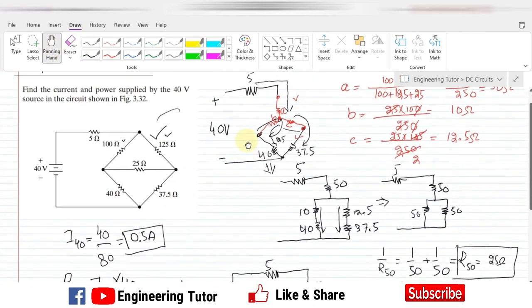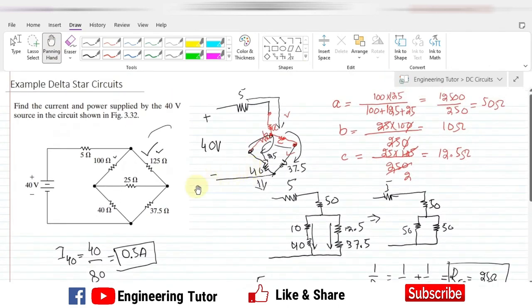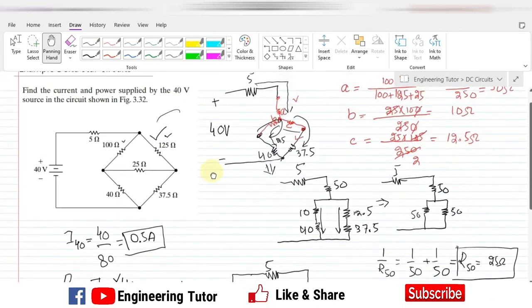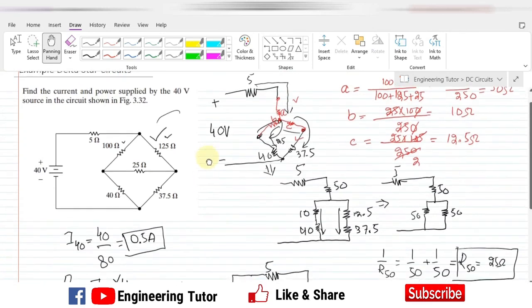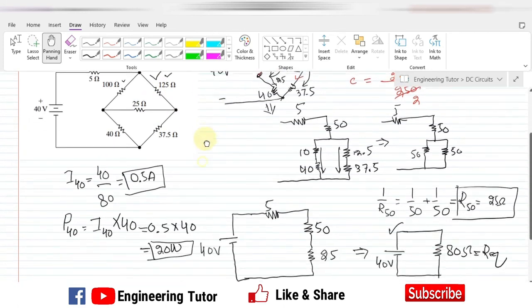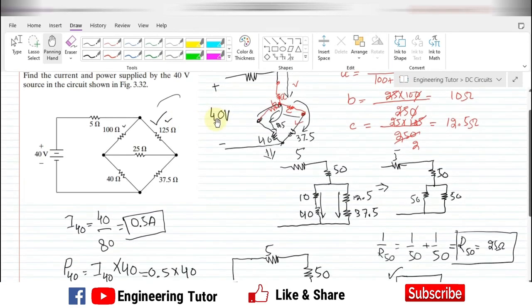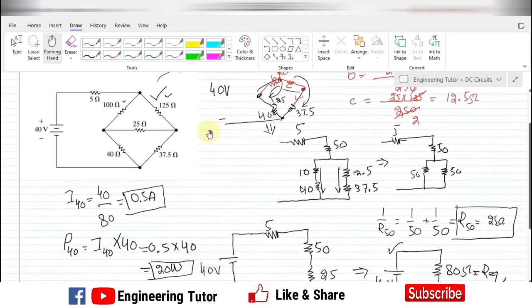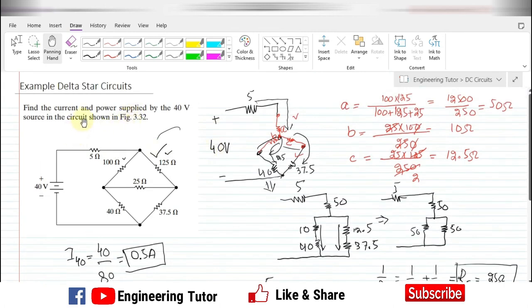consideration behind solving the circuit like this one is to see what are the configurations which are neither series nor in parallel combinations, and how to solve the circuits like those ones. So initially we have to find the equivalent resistance, pick any one of the two deltas, or any of the stars, and convert them into the other configuration, and you will see that is basically our circuit. And here we have used the conventional circuit laws to find out the equivalent resistance, and after finding the equivalent resistance, we found out the current and power supplied by the 40 volt source.